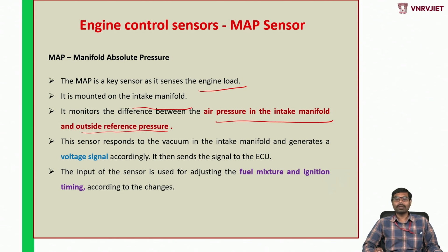If the pressure inside the manifold and the outside atmosphere are equal, then no air is drawn in. There should always be a difference in the vacuum.